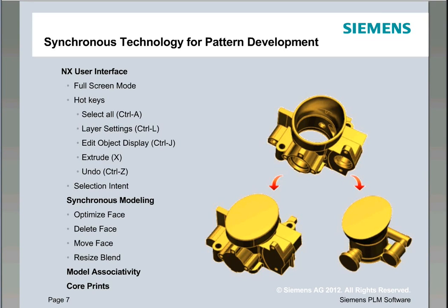I can delete and move faces, resize blends. Again, our models will be associative throughout the process, even the imported models from other CAD systems. And then lastly, I'll be working on core prints. So let me bring up my NX session here.